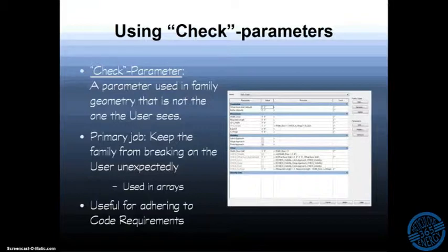The clear floor area family is built to have that 8-inch offset because that's what the ADA push-pull requirements are. I didn't make that up. I, as a family maker, would have no reason to arbitrarily limit the end user of this family, but when the limitation is imposed from the outside, I can keep the user from making an unwitting mistake.